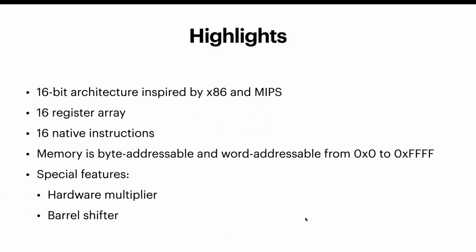The x16 is a 16-bit architecture inspired by x86 and MIPS. It features a 16-register array, 16 native instructions, byte and word addressable memory, as well as special features which include a hardware multiplier and barrel shifter.